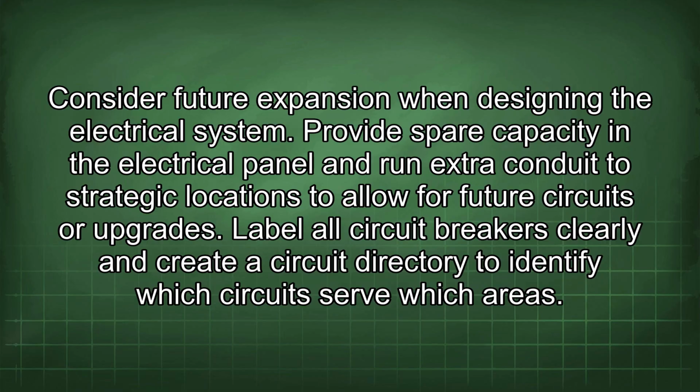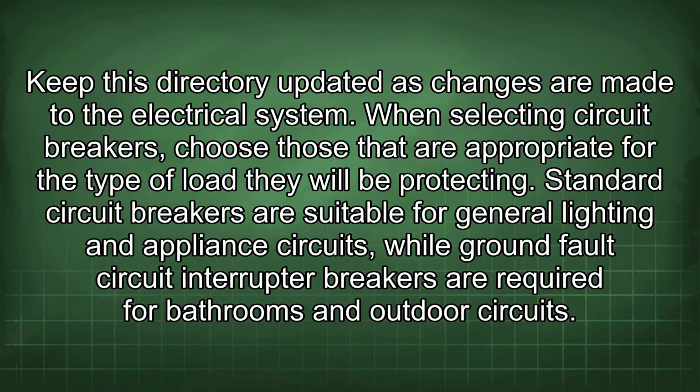Label all circuit breakers clearly and create a circuit directory to identify which circuits serve which areas. Keep this directory updated as changes are made to the electrical system. When selecting circuit breakers, choose those that are appropriate for the type of load they will be protecting.